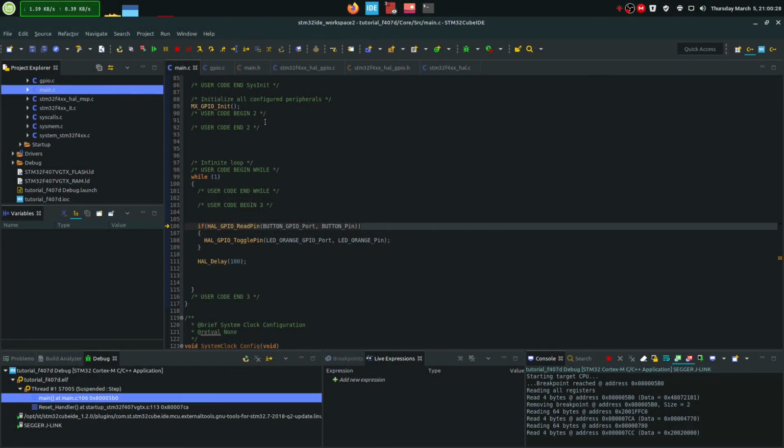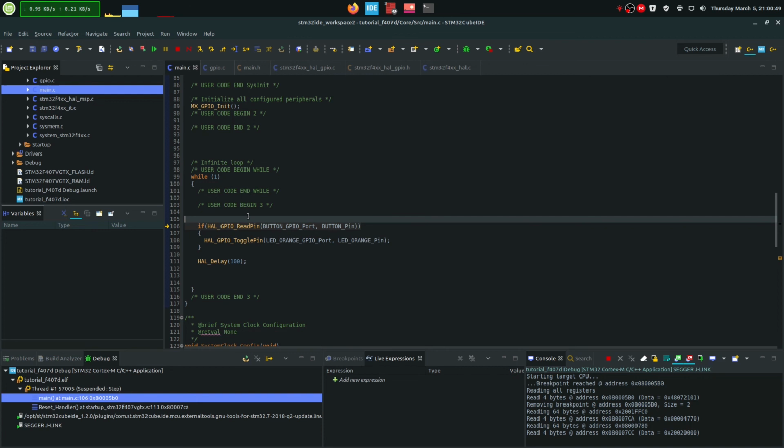According to my multimeter, which doesn't read anything other than over range, the resistance to ground of that pin is too big for the multimeter to read, and I believe this is quite a good multimeter and can read over 20 megaohms, so it really does what we thought it would do, so that's correct.